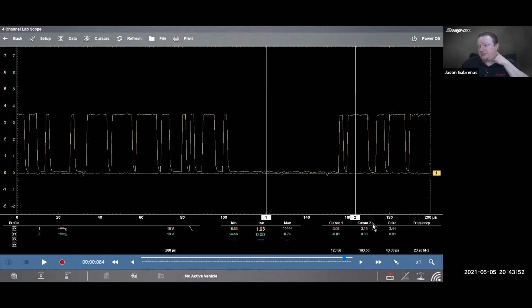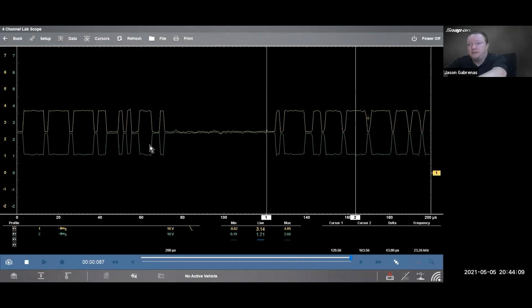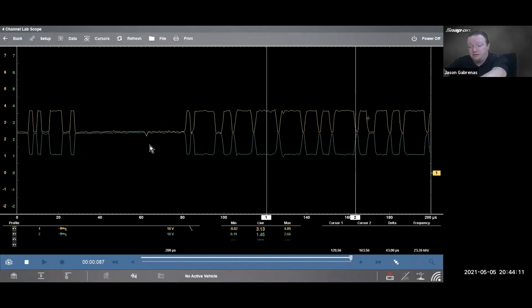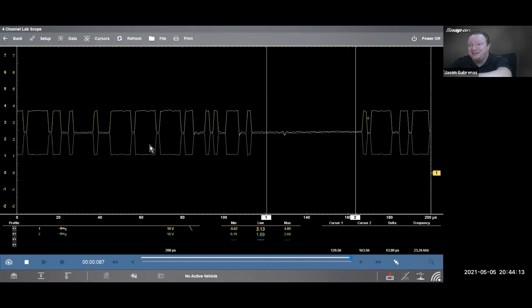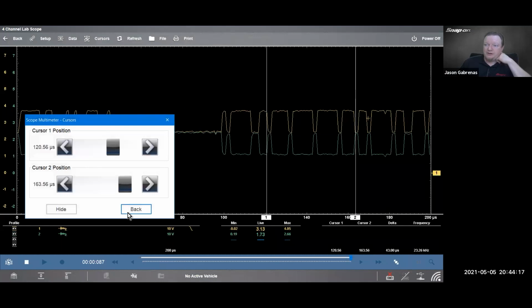When it transmits, we're getting 3.49 volts, which is about where we were, about 3.5 volts on the high side. So the high side still transmits, but the bottom gets pulled down to ground in this case. All right, so that's a problem. Actually, my high side's a little loose too. So, there we go. All right, so we got that. So that is low side shorted to ground.